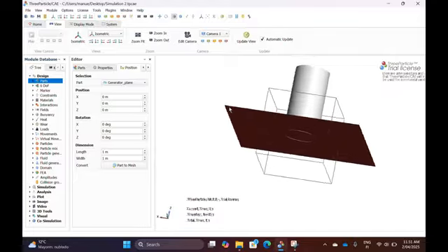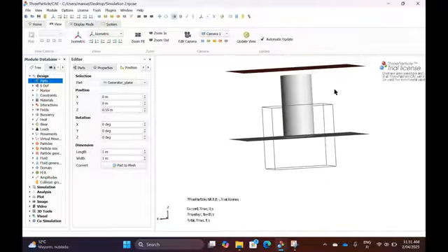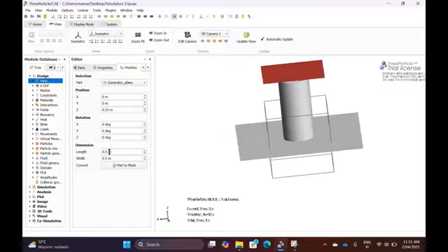It's already red. And we lift it up. That's the first thing. Place it above the actual cylinder, probably not that much above, something like 5 centimeters off the cylinder. So 0.05. Much too big, most of the particles would go on the sides, so we'll make that a little smaller. Like that. Should work, hopefully. Good. So we have that.